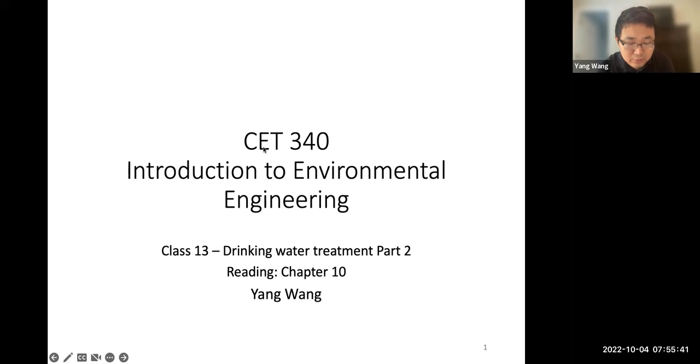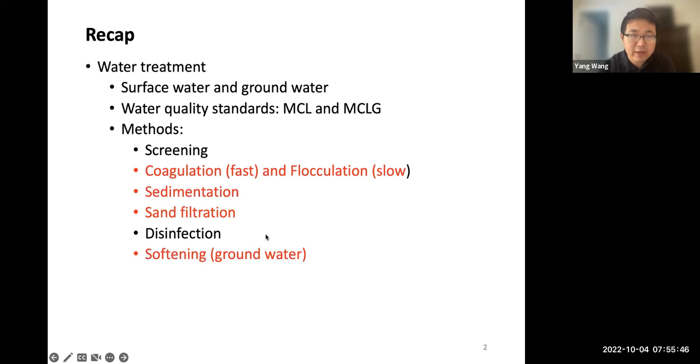This class, we're going to talk a little bit more about drinking water treatment. So, a quick recap of our last class: we mainly talked about different types of water for extracting drinking water. There's underground water, and there's also surface water. We said that underground water, or groundwater, is generally cleaner, but it has the issue of hardness, mainly because minerals get dissolved into the water. Those minerals are hardness ions, like magnesium ion or calcium ion. And when you boil the water, you're going to find those white scales.